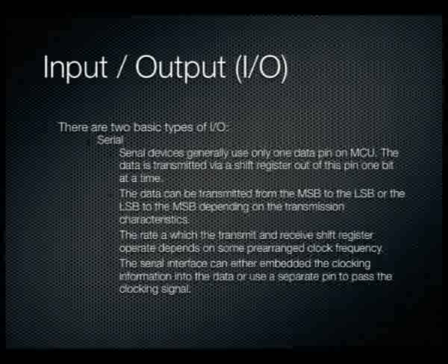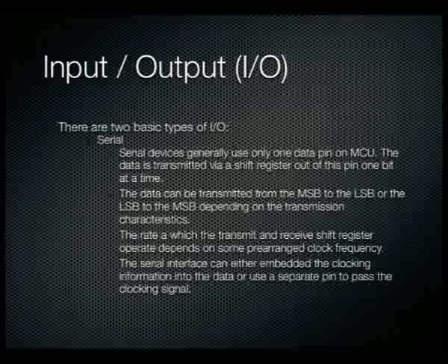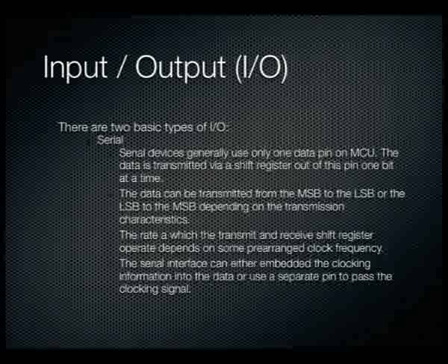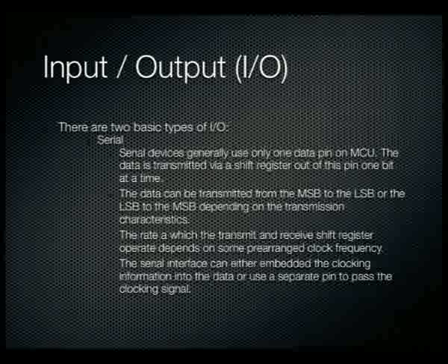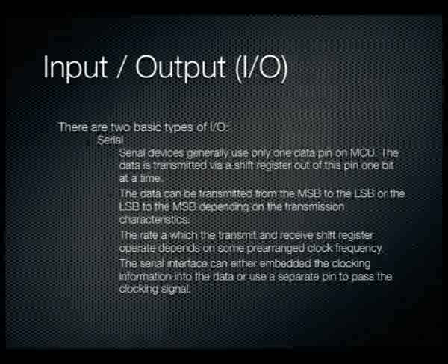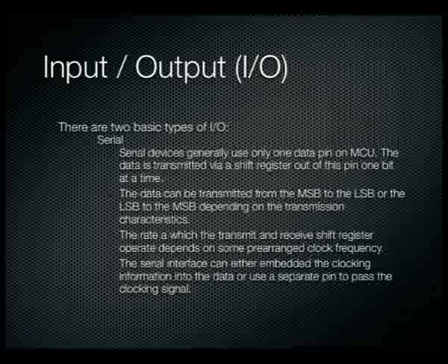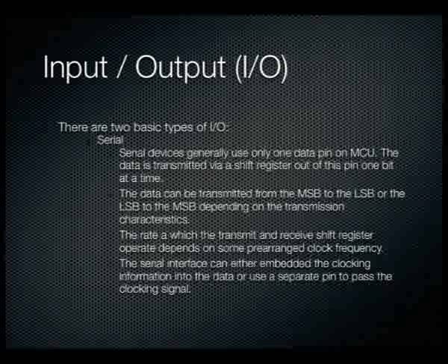With asynchronous serial communication, the clocking information is prearranged at both ends, and we're simply phase aligning that signal each time we send some data across. Or you can have the master generate the clock signal and pump it to all the other devices, so they don't have to locally generate their own clocks. So it depends on whether it's asynchronous or synchronous, and we'll talk about that a bit later when we talk about serial subsystems.